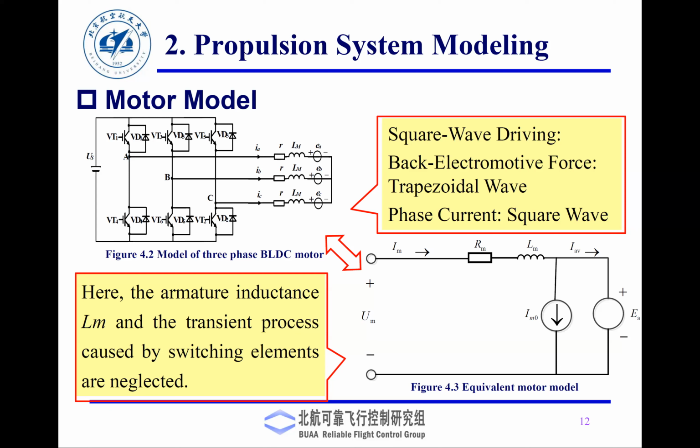And you sequentially operate those switches so that the DC current going through gets switched. Then instead of a straight constant current, you are going to get some sort of sinusoidal current. And this switching happens very, very fast. So that's why you get a three-phase output from a single DC input.